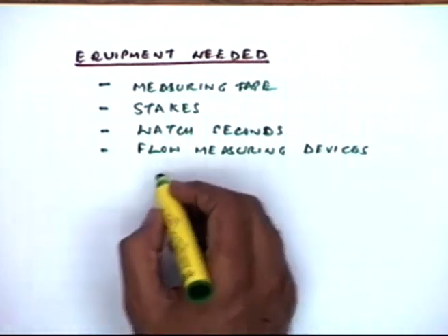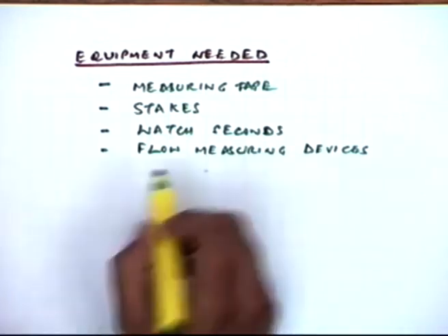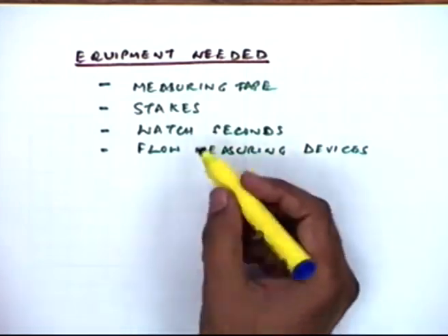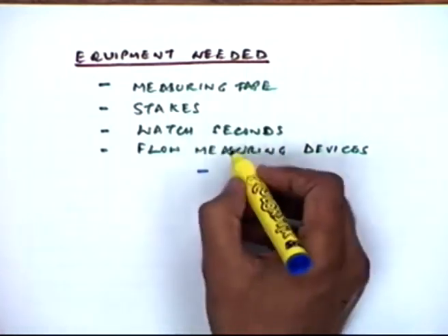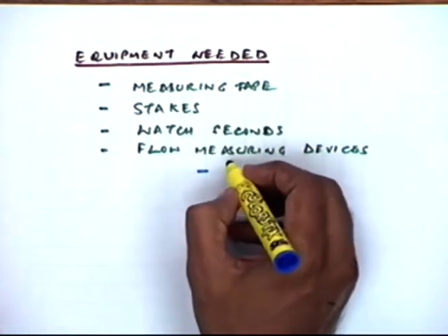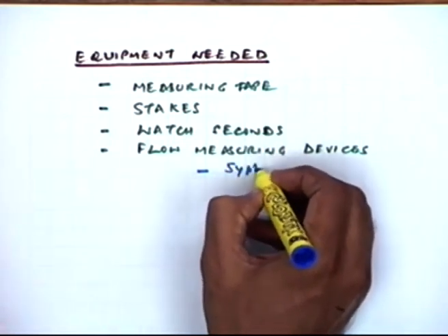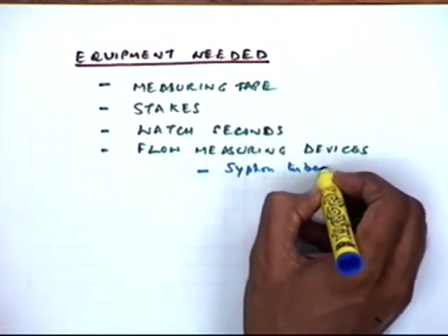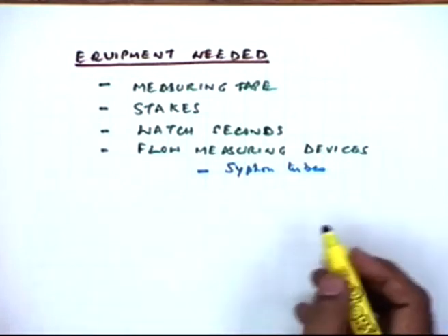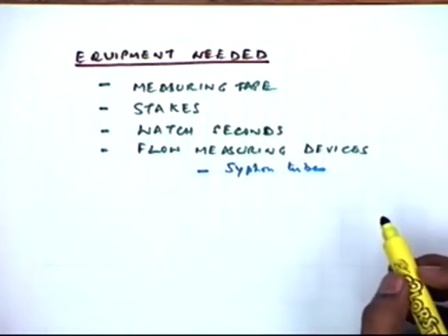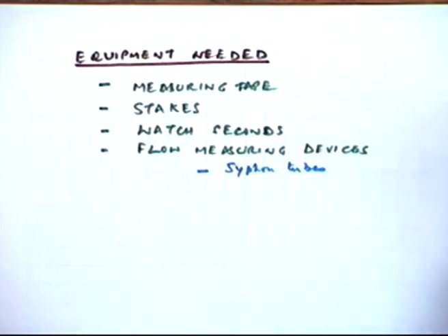We have earlier discussed that in some cases you use the siphon tubes, especially in the case of border irrigation. You use the siphon tube so that your waterfront is quite uniform, since the width of the border is quite appreciable.